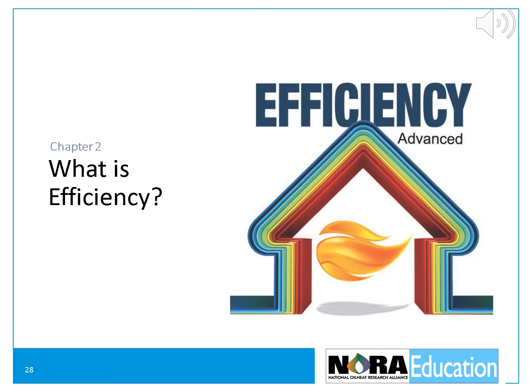Heating systems lose energy in many ways, starting when the pump delivers the fuel to the burner up until the heat reaches the living area. Some of these depend on the design of the burner, furnace, boiler, or water heater, the venting system, and distribution system. Additionally, how the system is installed, adjusted, and maintained will also affect the efficiency. Finally, how well the building envelope is sealed and insulated determines how long the heat created by the heating system stays in the building.